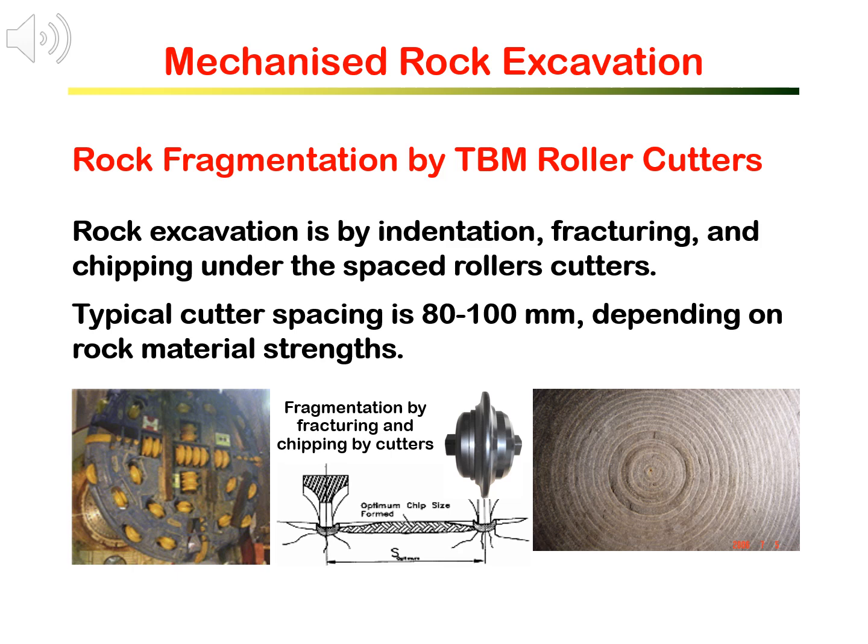The indentation marks by the roller cutters are clearly visible on the right photo, shown by those concentric circles. The mechanics of rock fracturing by roller cutter is governed by rock material strength and the cutter load.